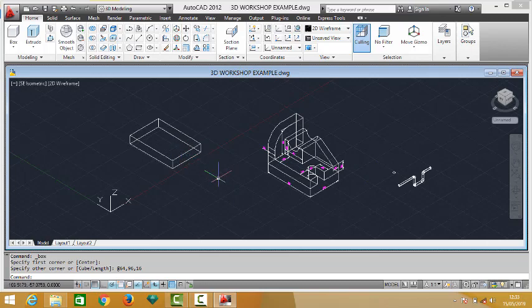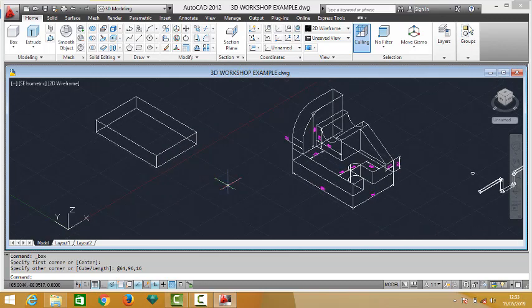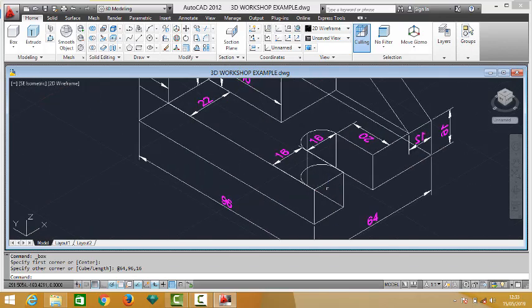I wanted to fix this direction. So whenever you have this kind of problem, just bring out your UCS to a visible place where you can see it by typing UCS. Tap enter on your keyboard, M for move, tap enter, and then click a place visible where you can see your UCS, so that you can define your X and Y coordinates. This is because I was interchanging the X and Y coordinate. That was why the rectangular profile was facing the opposite direction. So have it in the direction that I want it to be now.